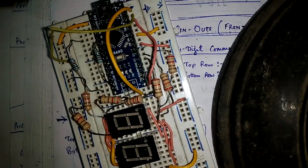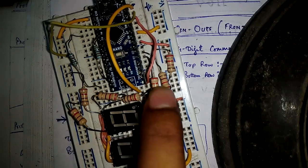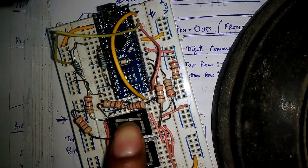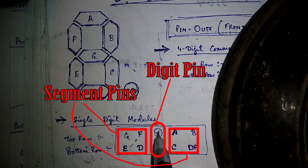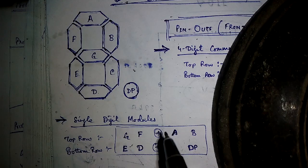So guys, this is my setup. As you can see, I have two options to connect these resistances. One is on the digit pin and another is on the segment pins. That means each of these segments has one resistor feeding one digital pin of my Arduino, and the digit pin is actually not given any resistances in there.